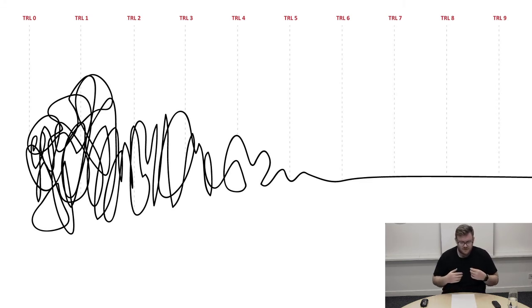It's not a case of scrap all the tools, let's start again. It's very much a case of, we've got to change the material. Do we need to change the tool a little bit to accommodate shrinkage, or there's more wear on a friction surface than we intended. Let's look at 5 other materials that might wear less, or how do we improve the tolerances of something. It shouldn't be a fundamental squiggle. It shouldn't be something so drastic it costs a huge amount of money, and that's if it's done properly.